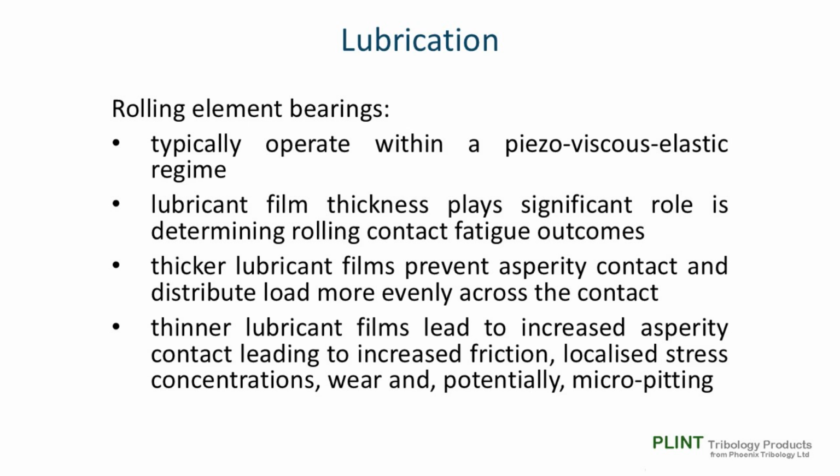A well-lubricated contact with a sufficient lubricant film generally leads to a longer fatigue life. This might suggest a preference for using higher viscosity lubricants. However, at higher speeds, this may result in increased lubricant shear and the bearing running hot, with the subsequent reduction in lubricant viscosity and hence film thickness. Satisfactory lubrication requires sufficient lubricant to be delivered to the in-running sides of the rolling contacts to ensure that inlets are fully flooded. If this is not possible, the bearing may run starved of lubrication, resulting in premature failure, possibly through seizure.